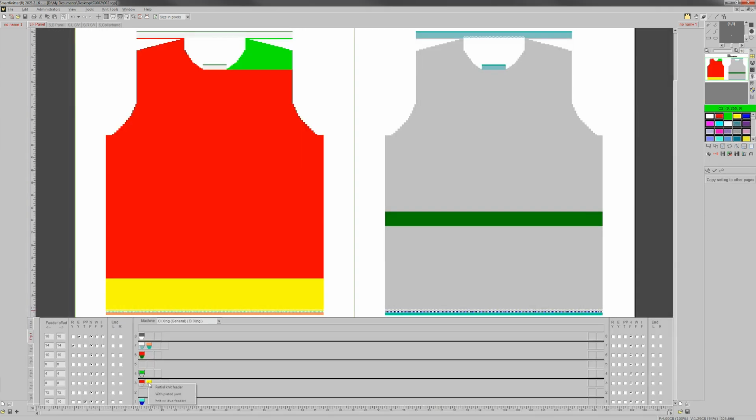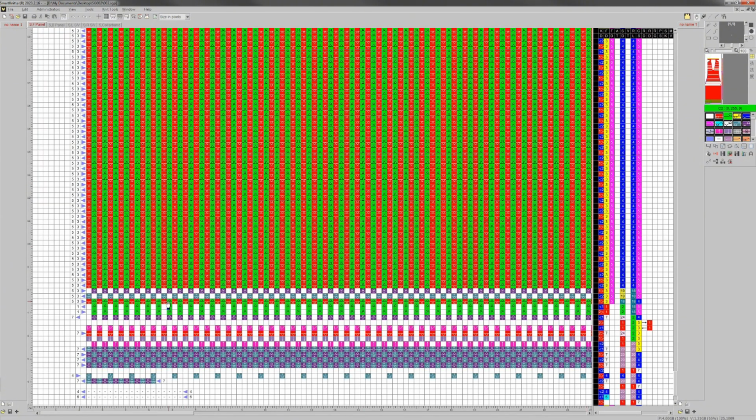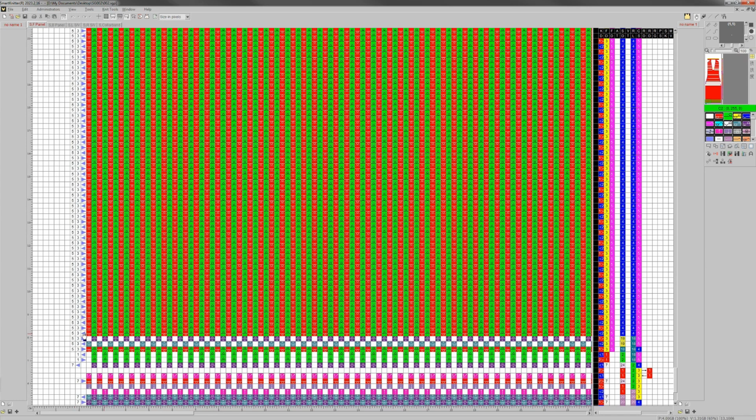Next, let's add a plaited yarn for the sweep. Zone 3, yellow. 1A represents the main yarn, while 1B represents the plaited yarn lycra elastane. Drag the icon to the appropriate feeder. As you can see in the machine code, feeder 3 and 5 are used in knitting the sweep, where feeder 3 is at the front.